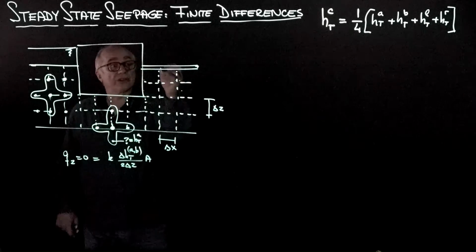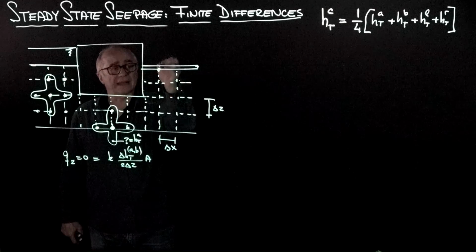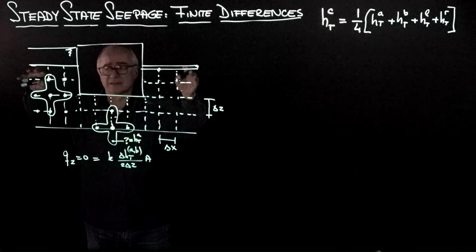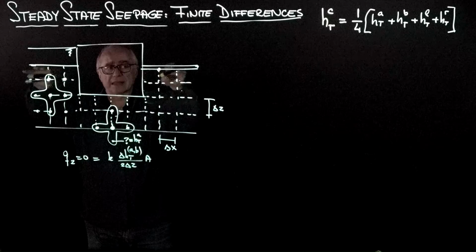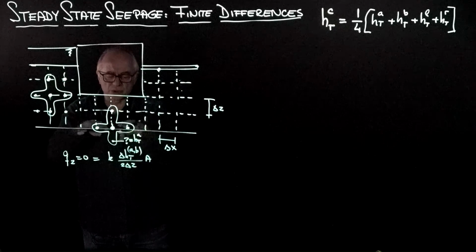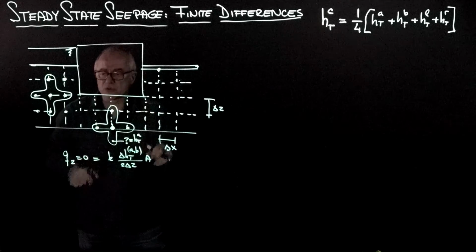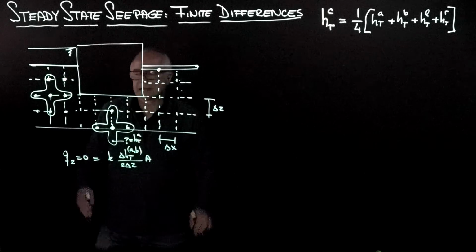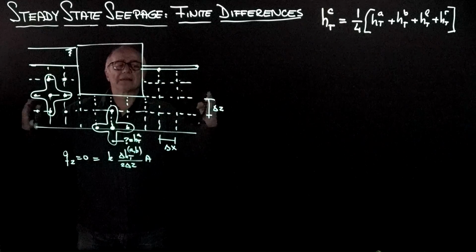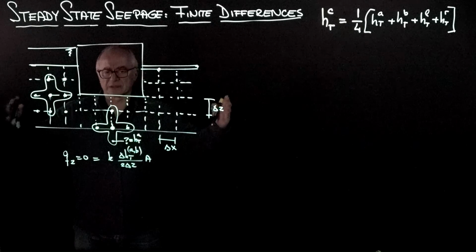Of course, I don't need to place the cross at this point because I know the total head on the boundaries, the first and the last equipotential. The tricky thing is, what do we do where there is no flow across the flow boundaries? The other question is, how far are you going to place the horizontal boundaries?